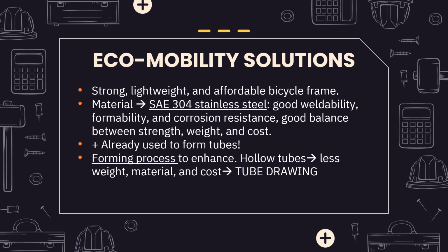And then the forming process chosen is to use hollow tubes because, as you reduce the material, you reduce the cross section, you are obviously reducing the weight and the costs. This process is named tube drawing.